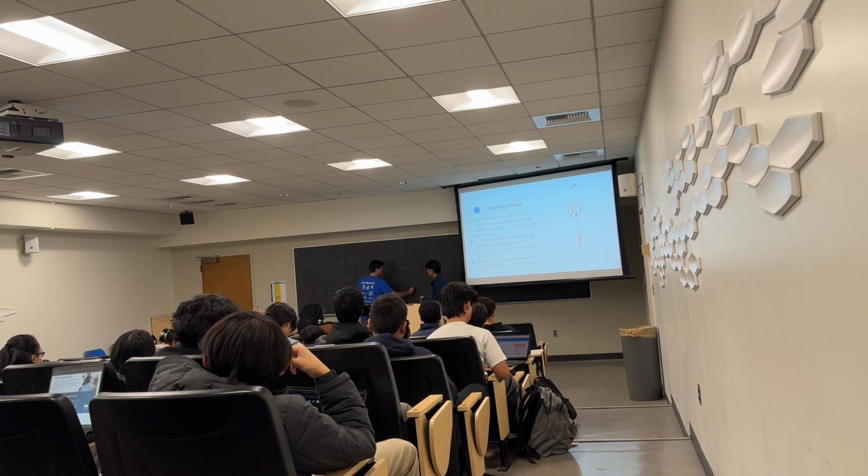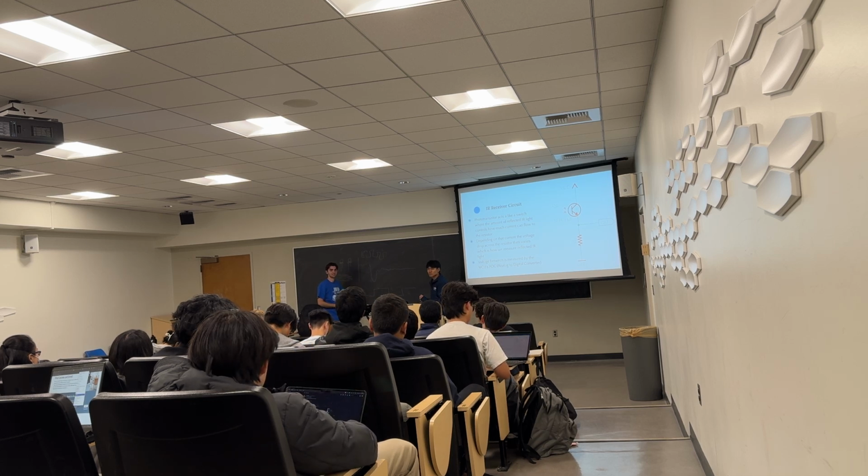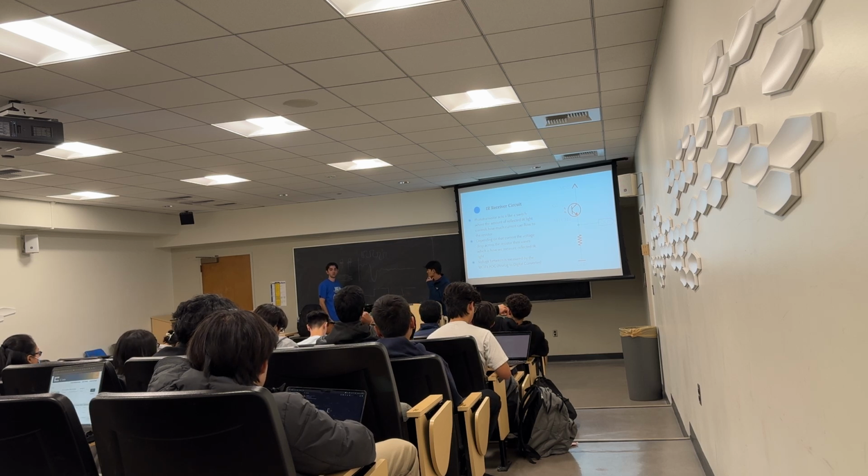Okay, you see that? Basically it knows the frequency here is really slow compared to when there's a high voltage. It might send something like this, where it's really fast. And so that's how your MCU can differentiate between the values in a digital format. Does that make sense? I think so. So basically, you just change the duty cycle to match.